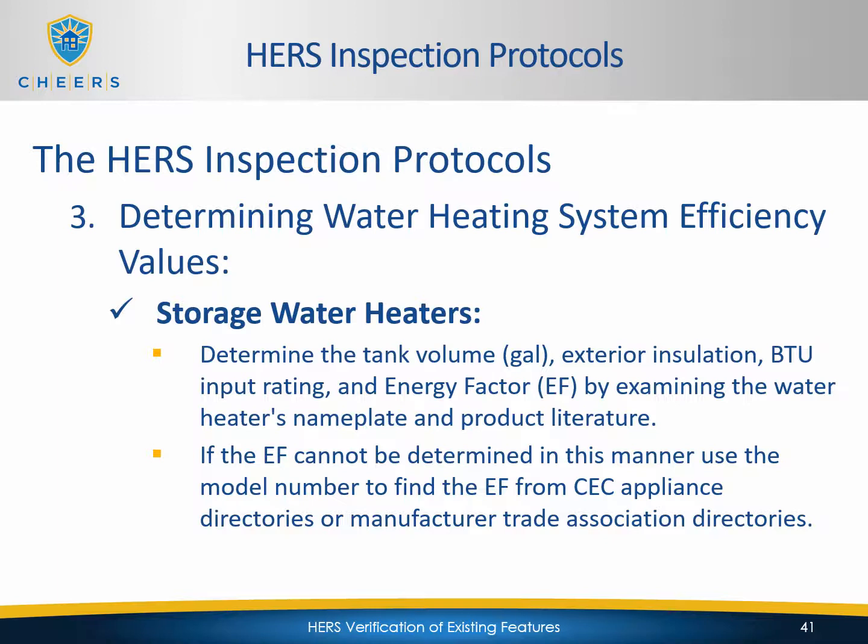Storage water heaters. You want to determine the tank volume in gallons, exterior insulation, BTU input rating, and energy factor by examining the water heater's nameplate and product literature. If the energy factor cannot be determined in this manner, use the model number to find the energy factor from the CEC Appliance Directory or Manufacturer Trade Association directories.